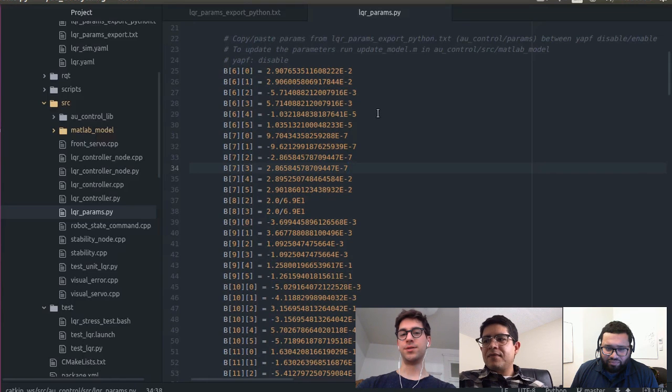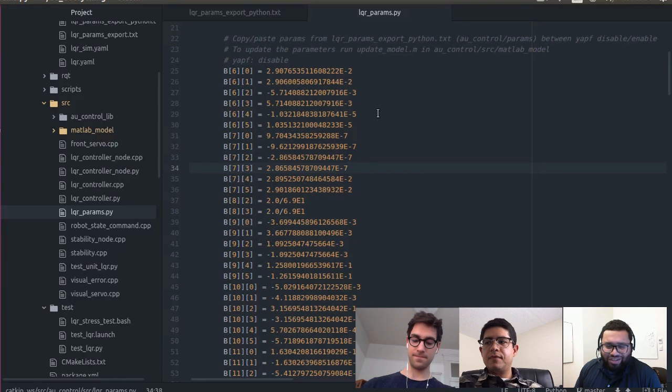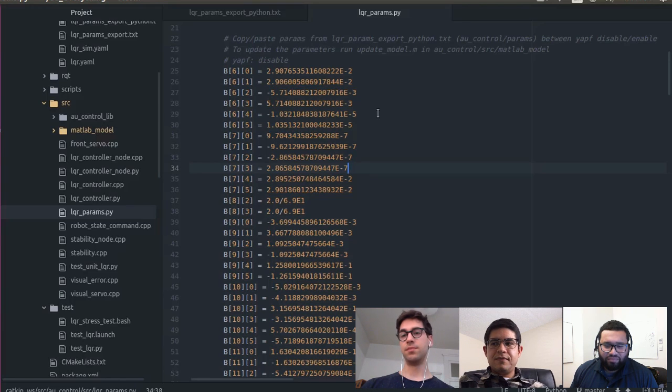Yeah, so the PID controller worked really well for basic movement, but one of the challenges during one of the years was to actually move in as many degrees of freedom as you could through a gate. So basically doing barrel rolls and complicated maneuvers. I believe they call those style points at RoboSub, right? Yeah, so with that requirement, the PID controllers just weren't going to cut it. So that was the original inspiration, but as we went forward, the ease of tuning and the flexibility is really what won us over in the end.